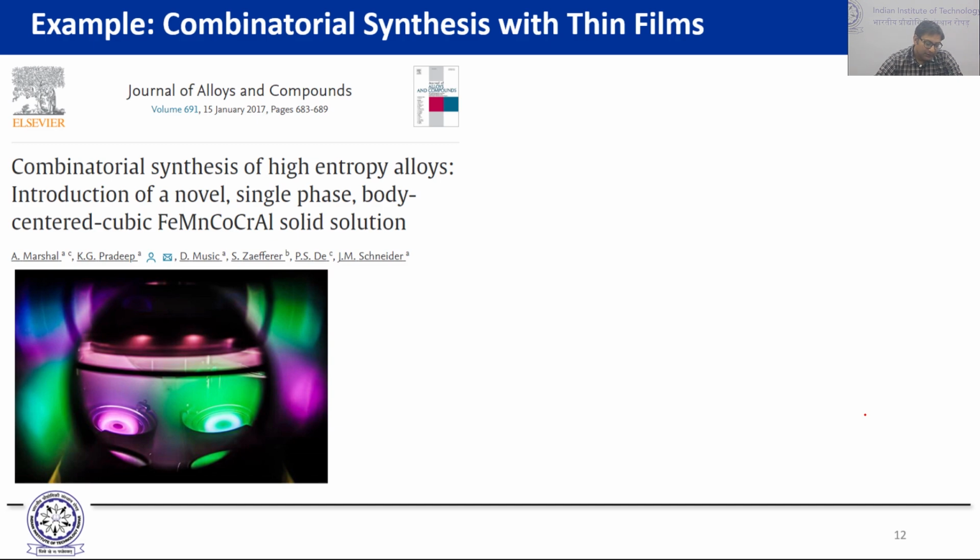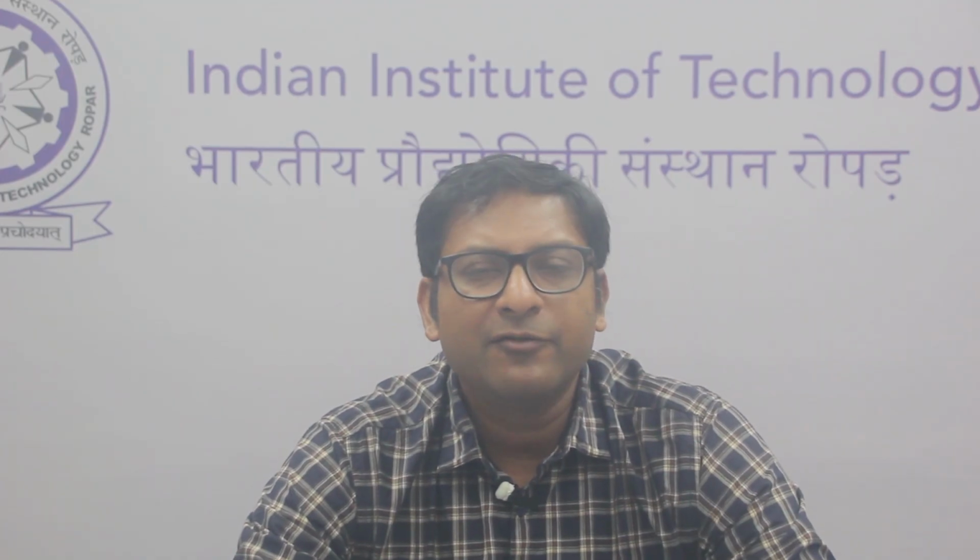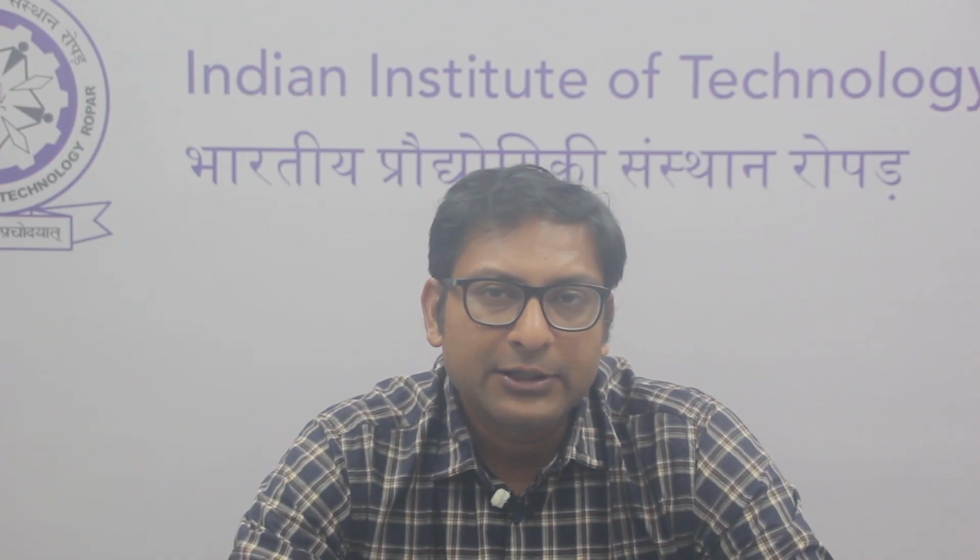Continuing with our examples, here's another example of combinatorial synthesis, and this time people have been using thin films. Now, what you will see is that using approaches like thin films, where you can control the process parameters to get a gradient of composition, or using different types of additive manufacturing, where you can program the powder feed rates in order to ensure you get composition gradients or maybe multiple alloys with slightly different compositions, you will see that these two types of processing techniques are extremely common.